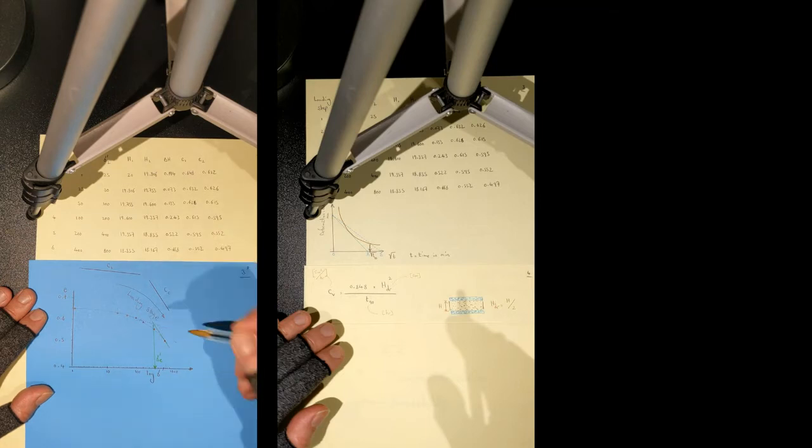So you will find the point of maximum curvature in the e-log sigma dash v curve, and you draw a horizontal line. Then you will draw a second line, which is tangent to the point of maximum curvature. And then you will draw the bisector between the horizontal line and the tangent line, and that is your dashed line, the bisector.